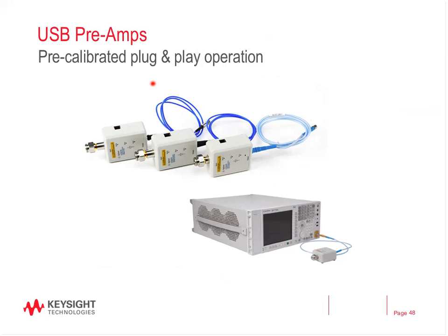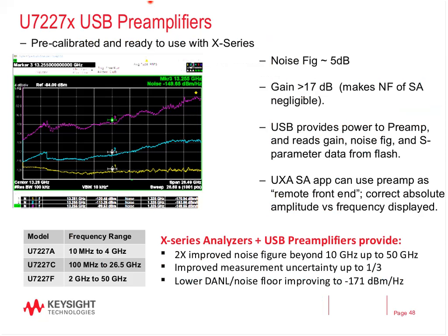Now the other option to you, instead of turning on noise floor corrections, or in combination with it, is to turn on an internal preamp or an external preamp. What's new, which I would like to highlight today, is our new external preamps. What's nice about these external preamps is you can extend the dynamic range of not only your existing spectrum analyzers, but even some of the newer ones as well.